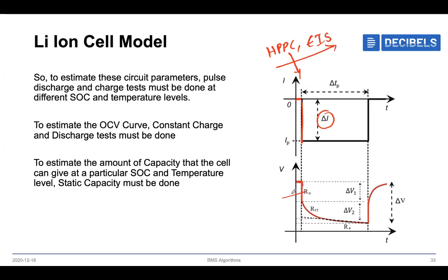So this sudden drop in voltage corresponds to an ohmic resistance. And after that, we have some variation, a delayed response or curve behavior of resistance. This is called RCT, charge transfer resistance, which means when we have an electrode inserted in the electrolyte, the charge will be transferring from electrode to electrolyte. So there will be some resistance between those things. That one is the polarization resistance.